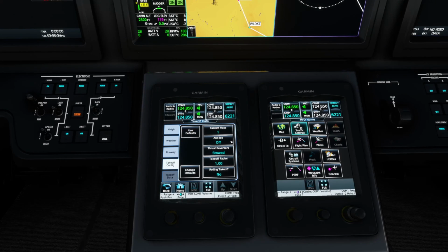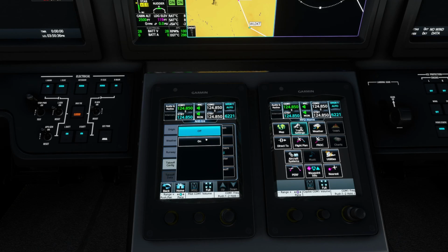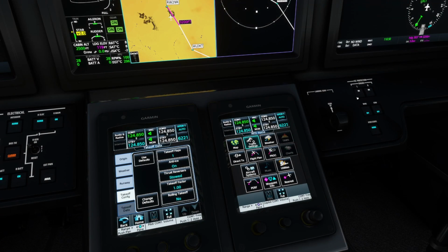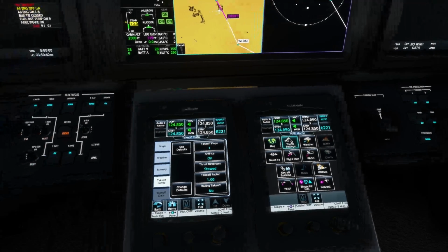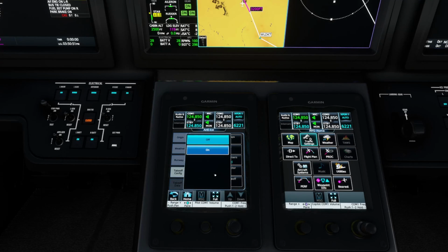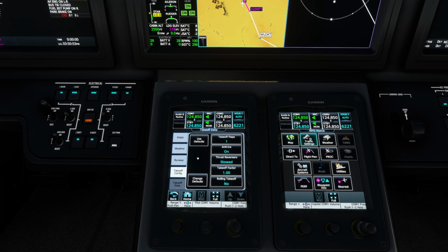We're looking for flaps 1 today. Anti-ice will actually be on. It is pretty darn cold, which means it's going to get even colder as we climb. Actually, we'll leave anti-ice off for now, but we will be turning it on before takeoff. All right, and again, if you need to change it, you can hit use default and it'll switch it back to what it was, but in our case, we're going to use it like this. All right, and we've got all of our origin information, and you have access to the flight plan page from here.